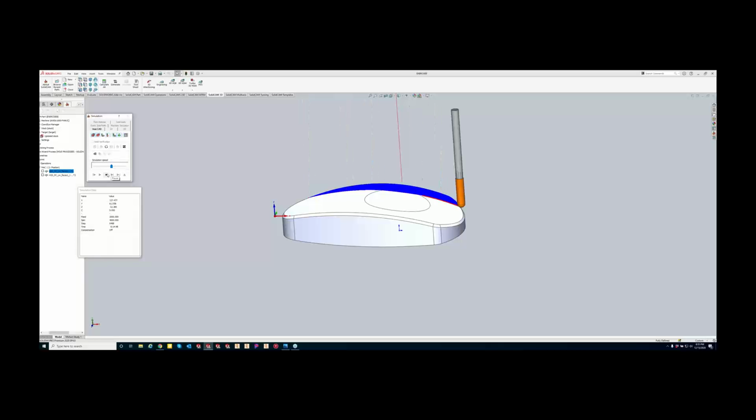Tim wanted such a small step over. Okay, so now if we go into single step mode, you can see that we're over that hole right now. But we also are going a much faster feed rate versus now as we get onto our current drive surface, our feed rate is going to drop right down to that 1,000 millimeters here. So it's a great way to really control your feed as it's going through that cut, and we're not wasting time over doing a standard feed rate through there.